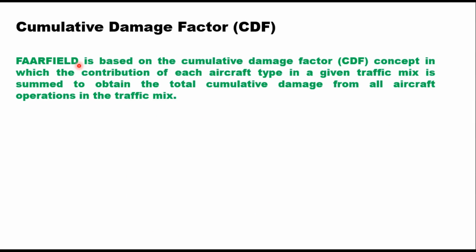Design with FAARFIELD software is based on the cumulative damage factor, in which the contribution of each aircraft in a given traffic mix is summed up to obtain the total CDF from all aircraft operations in the traffic mix.